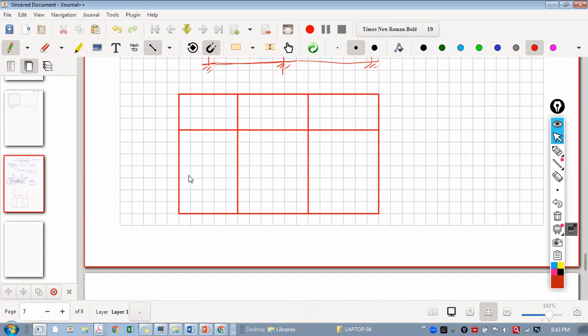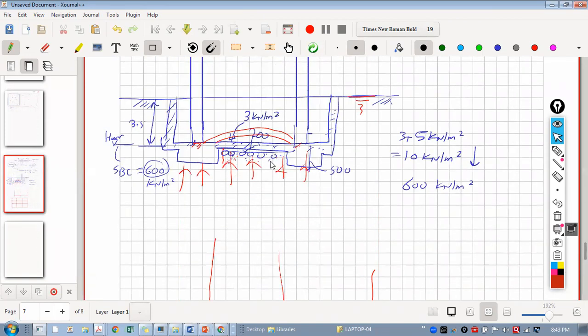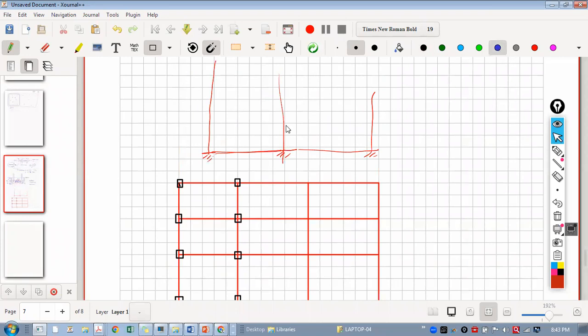If we have beam to beam connection also at that level, then can we design it one way or two way? Yes, definitely. If you are providing beam, say, let me draw this. Let's say we are having columns like this. Here we are having columns. So there are two ways: either you can do the flat slab. In that flat slab, you know that we have a column capital. So this will be your column capital here.